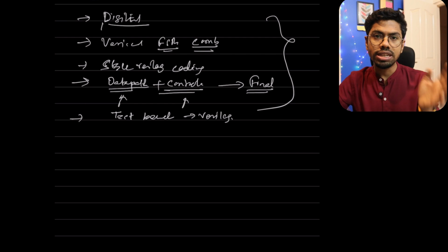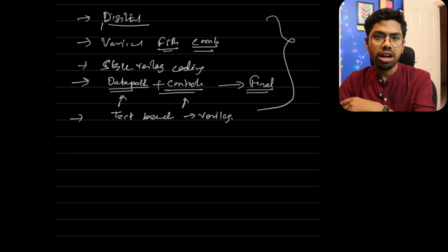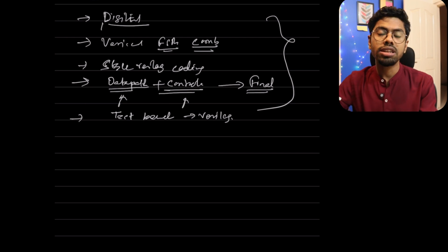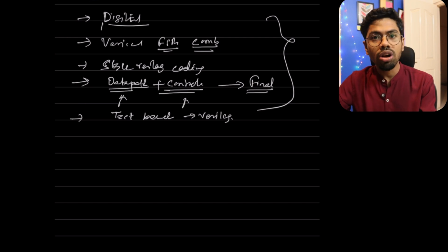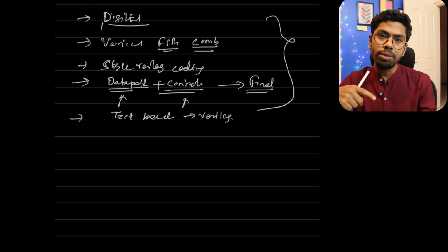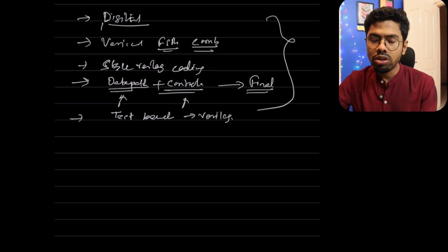First of all, we need to design a register, right? The instruction register, and then the decoding part. Those we will go through in detail. We'll write the code, and we'll execute it to see if it is working or not. We will also see the theory behind everything, for the ALU and for the logical unit too.